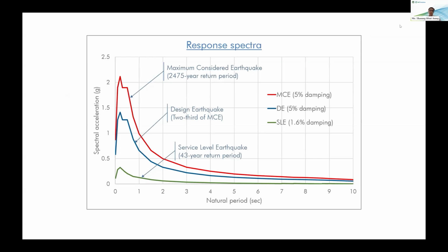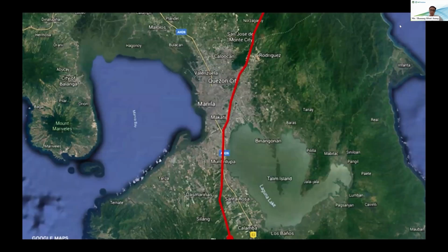PSHA consultant provide the response spectra for normally 3 levels of earthquake. One is maximum considered earthquake, which is 2475-year return period, and design earthquake is 2/3 of MCE, and service level earthquake is 43-year return period with different types of damping.